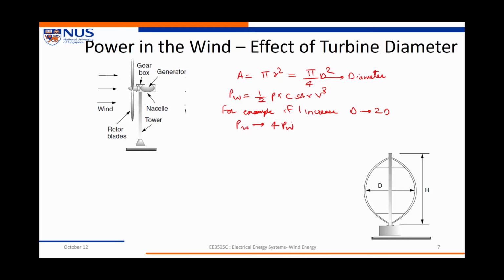by a factor of 4, while the cost of a turbine increases roughly in proportion to the blade diameter, but the power is proportional to the diameter squared. So bigger machines have proven to be much more cost effective in the case of horizontal axis wind turbines.